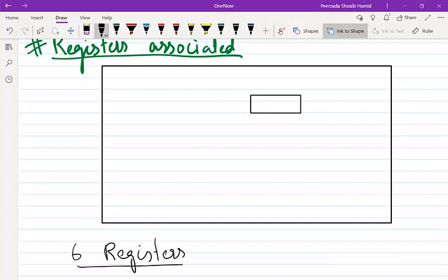Let me discuss the registers with timer 0. Same will be the case with timer 1 and timer 2. The only difference is that some of the registers in timer 1 will be 16 bits. So this is for timer 0 only. The first and most important register is the counter register, in which we count the numbers, which auto increments at a given rate, and that register is the timer counter, T, C, N, T.